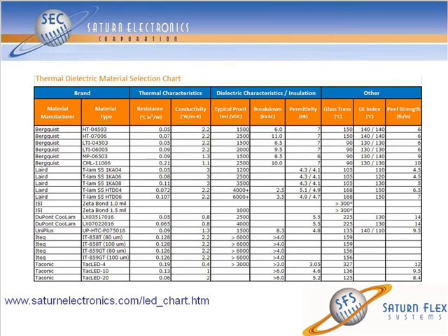As an OEM who buys the final product, you will never receive a PCB that has B stage material in it. It will fall apart. You receive C stage. So shouldn't you be calculating all your performance, your thermal stack-up, if you will, using C stage values? And if they're not available out there, then they really should be.